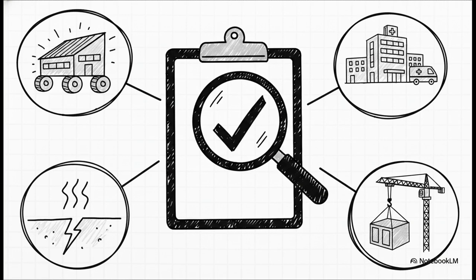Look, relying entirely on the original design team to spot their own errors is a major blind spot. That's why independent proof consultancy is absolutely mandatory when triggered by 4 high-risk scenarios. We're talking innovative designs like base isolation, high public risk projects like hospitals or metro stations, extreme seismic complexity involving nonlinear analysis, and modular construction. Modular is huge right now, but it introduces totally unique temporary lifting and transportation loads that just don't exist in